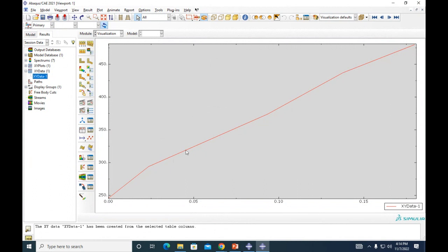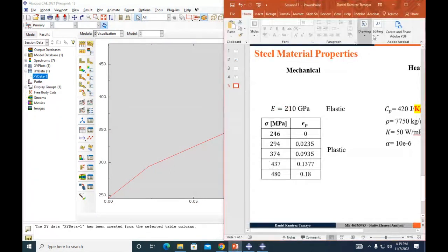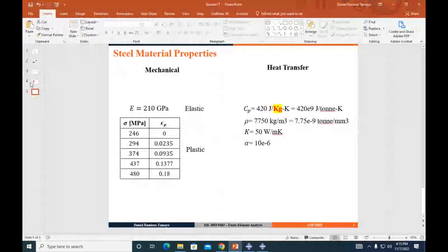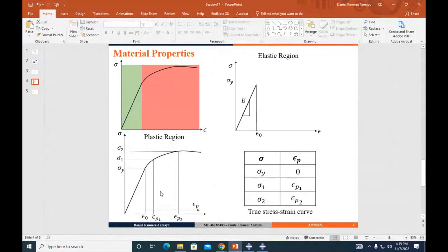And then this is showing how much deformation you have after you apply stresses, right? How much plastic deformation you have in your system. This doesn't look like a curve, right? But believe me, it's something like this. So we are just modeling, adding this information into Abaqus.